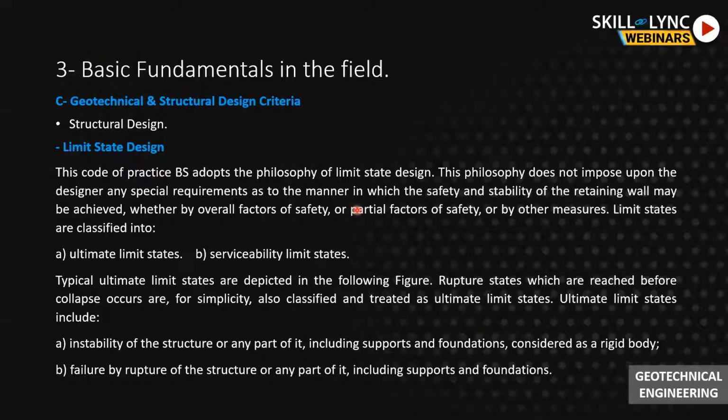In the ultimate limit state, we design our wall to resist the straining actions like bending moments and shear forces. We can also design the tieback anchors, steel struts and their connections, anchor bolts, and everything. We can also check the overall stability, the overturning of our shoring system. Secondly, we apply the serviceability limit state, which is the movement of our walls. If it's a permanent structure, we can apply other checks like crack widths, depending on the project specification.